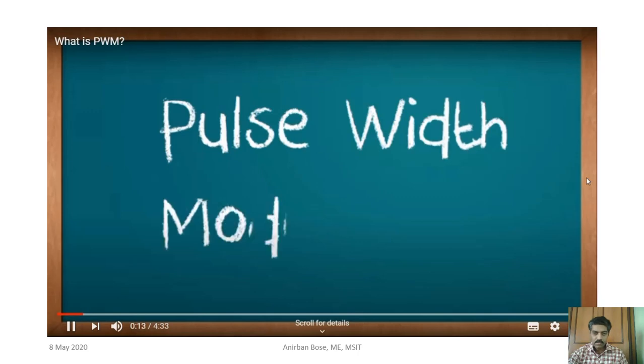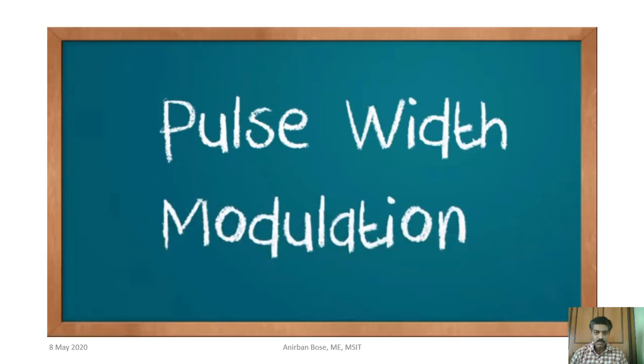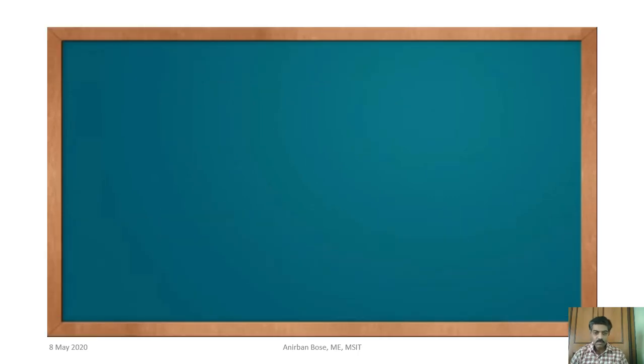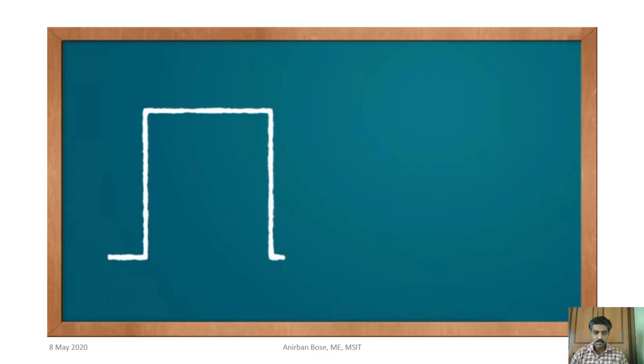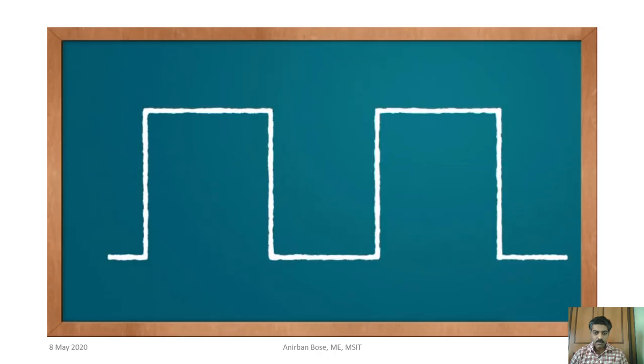PWM stands for Pulse Width Modulation, and it consists of producing a square wave whose up or high time you can control. In a PWM signal, the minimum and maximum voltage are the values that limit the wave's oscillation. The space between them is called amplitude. A cycle is the interval of the wave where you can find one full repetition.